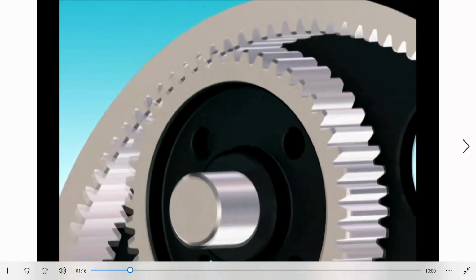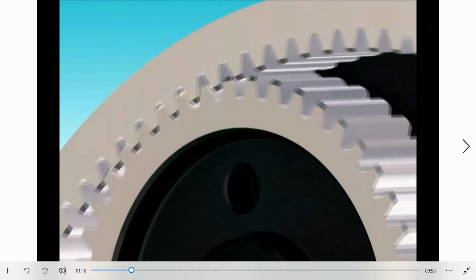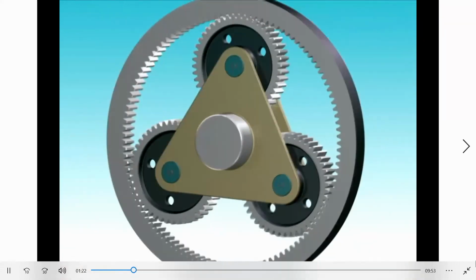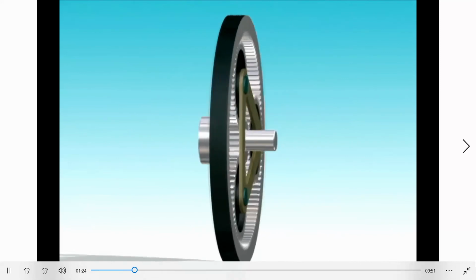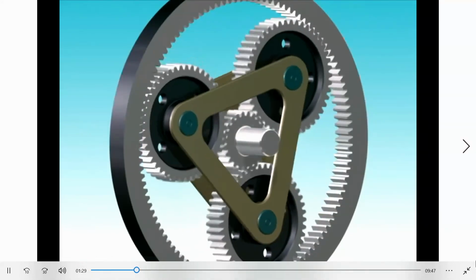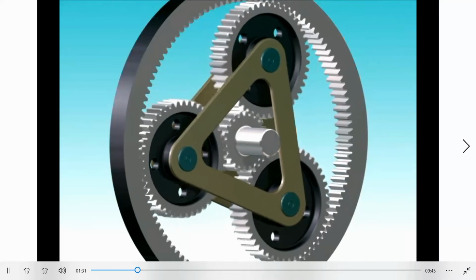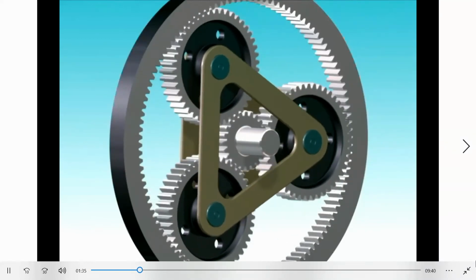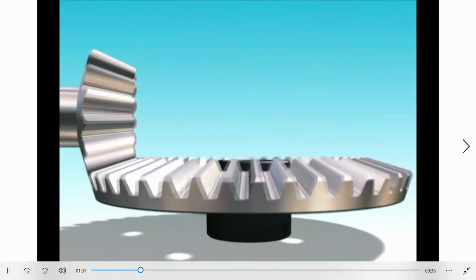Cylindrical gears may be internal and external. So-called planetary gear is based on the transmission with internal gear, and it is characterized by a large gear ratio and high kinematic accuracy. Planetary gears are used in automobile industry and aviation. They are more compact since the torque is split into separate strings. In this case, the torque is split into 3 strings.